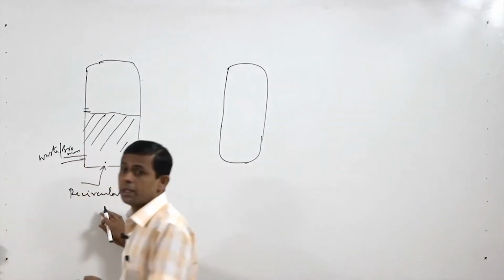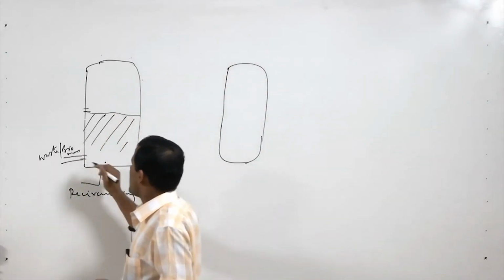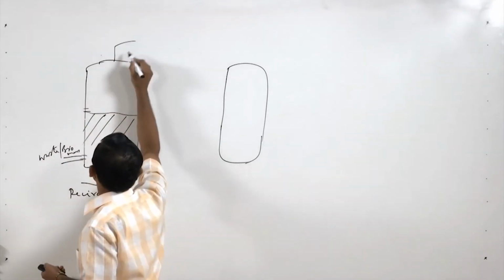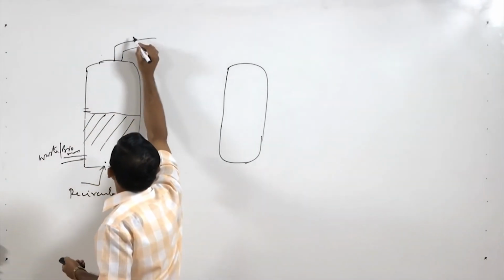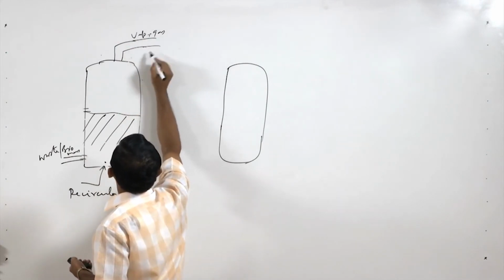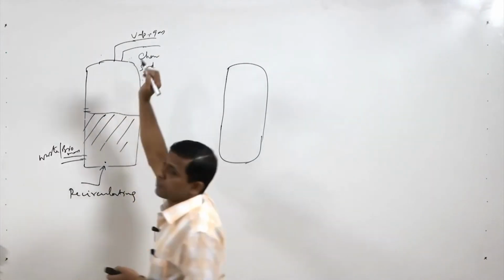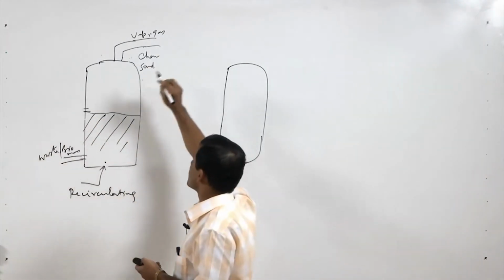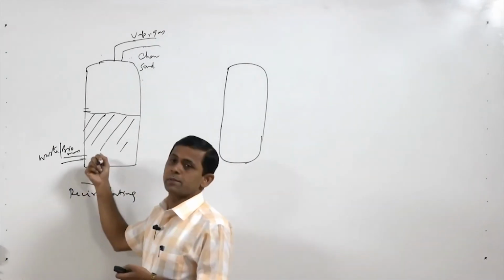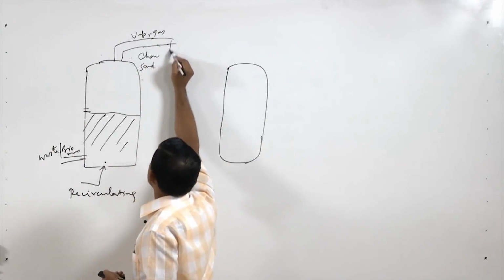Recirculating gas, where does it come from? It comes from the second chamber. Here the pyrolysis takes place. Pyrochar along with vapor, gas, char and sand all come from the top of this pyrolyzer, because high velocity is maintained here. It is coming, then it is separated,